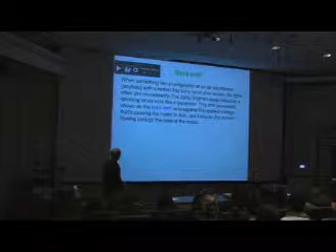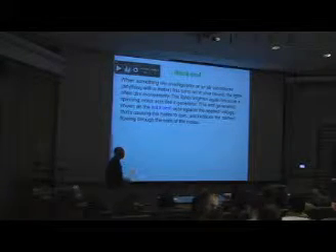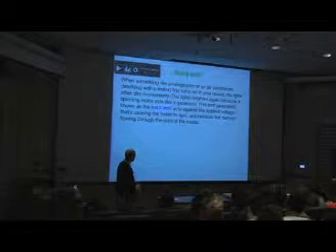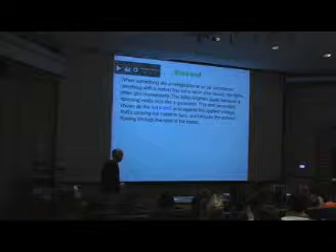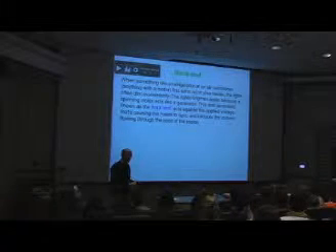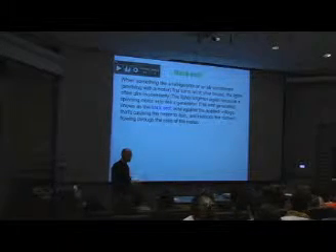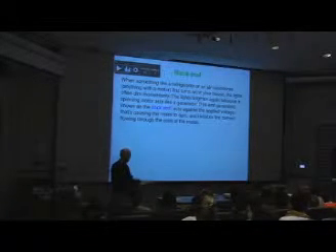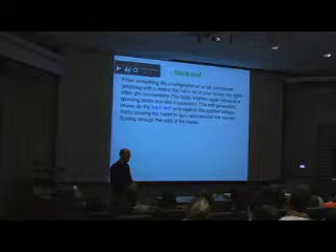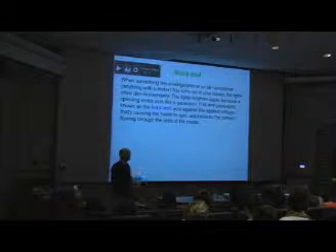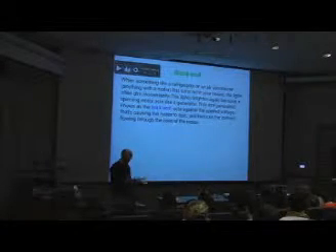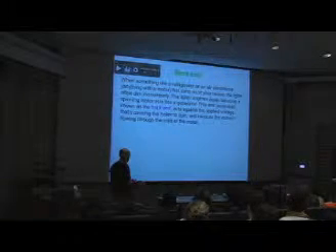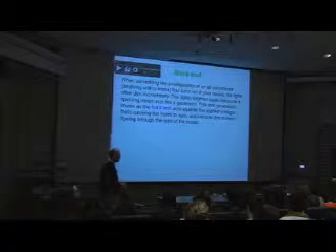And so what happens here is anything that has a motor in it, like a compressor in a fridge or a compressor in an air conditioner, is a good example. What does the motor need to do when it turns on? It spins, and it's a coil in a magnetic field. So what does a coil do in a magnetic field? It generates its own voltage. So a motor, just by its very nature, when it's operating, spinning, actually also acts like a generator at the same time. Can't get around that.